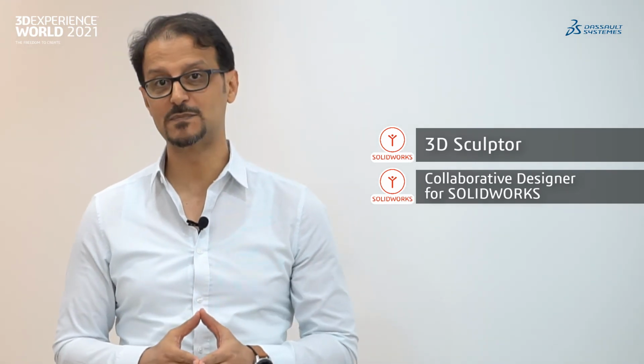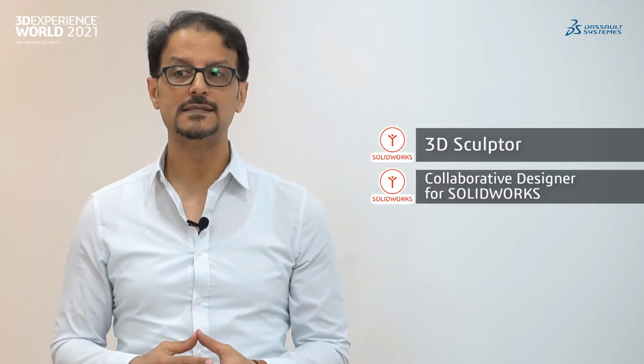And we are done. So what we have done so far, we started from a concept design, from creating all of the components initially in SOLIDWORKS that have been stored in the 3DEXPERIENCE platform, bringing them all together into SOLIDWORKS. And from there, we have been using xShape. xShape is included in the 3D Sculptor role in the 3DEXPERIENCE platform. And I can call this advanced surface modeling for us as SOLIDWORKS users. And from there, we have been able to create the organic shape using sub-D modeling.